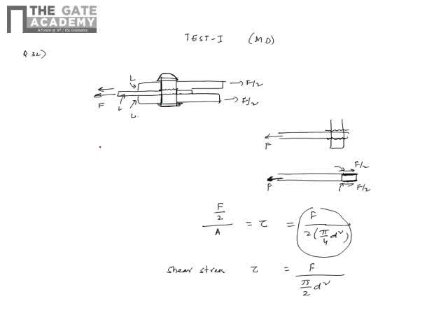So if you consider the top plate, this is the left half cylinder, and this will be in contact, right? Now the crushing stress is defined as the total force that is resisted by this half, the semi cylinder.